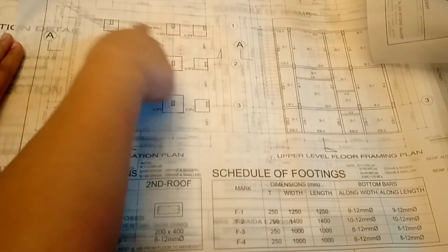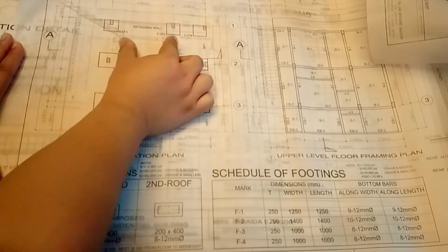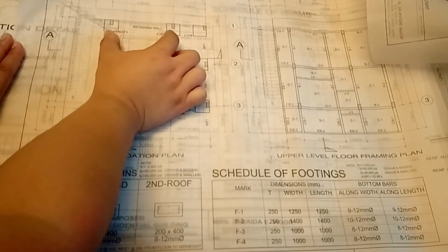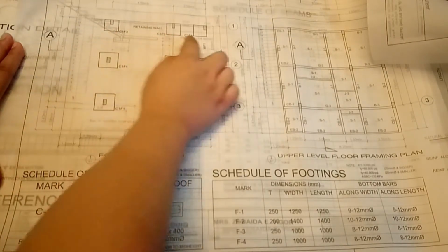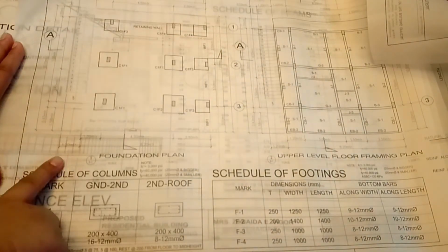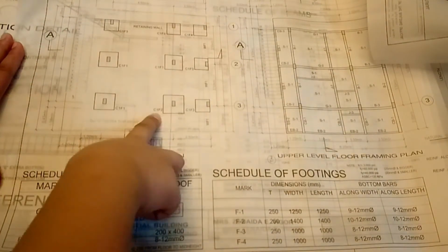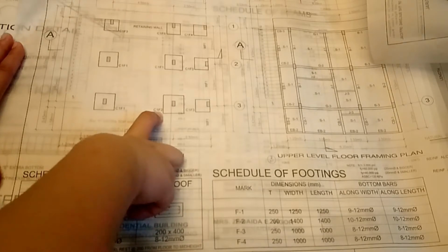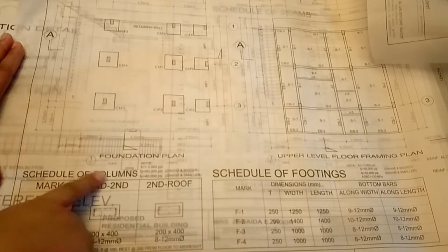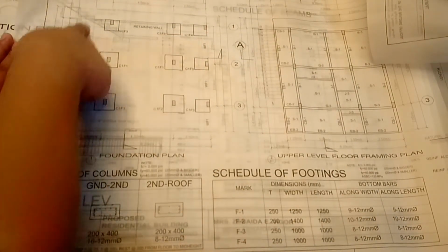So F3 means the size of the footing. Okay? So this means that these two structural components here have the same dimensions, thus it's C1F3. While this one, C1F4, is the same column size but a different size for the footing. Okay, so that's the concept, class, of naming those different structural components in your foundation plan. Okay. So at the back of the wall here, we have a retaining wall and we have the stairs going up.